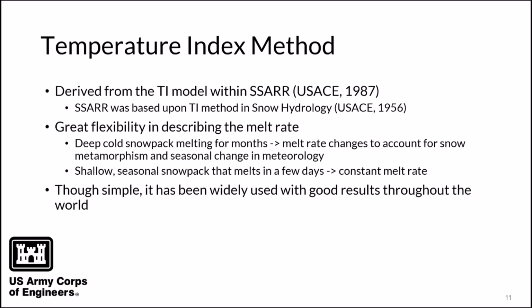It came from that. Temperature index, though it seems simple, has really been used widely throughout the entire world to represent the accumulation and melt of snow. We only have the ability to represent energy inputs with one term, the air temperature itself, but we can do some cool stuff with the melt rate to allow that to change throughout a simulation.